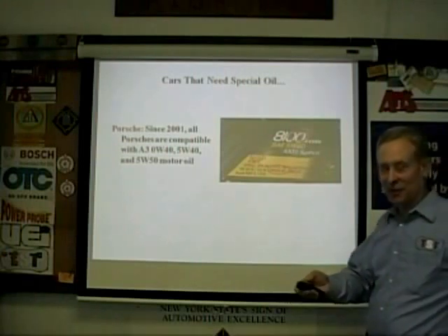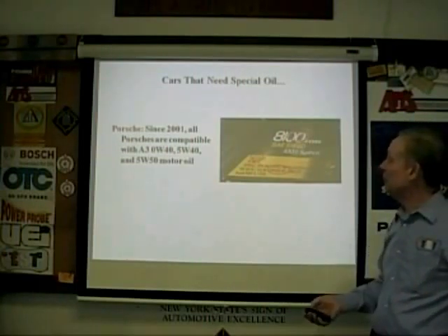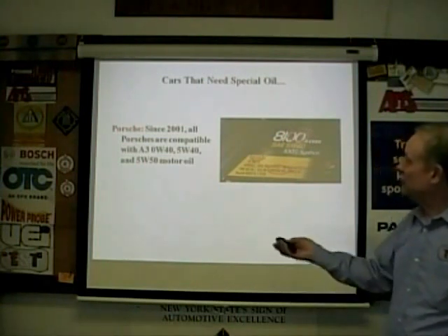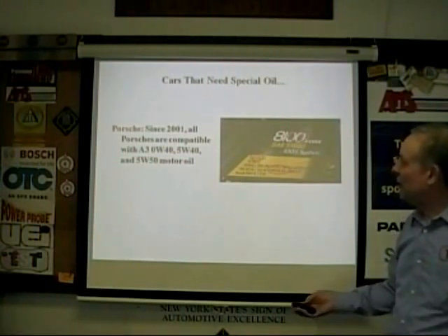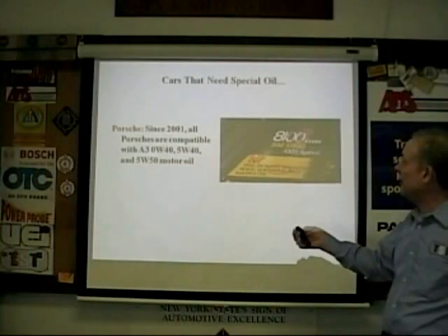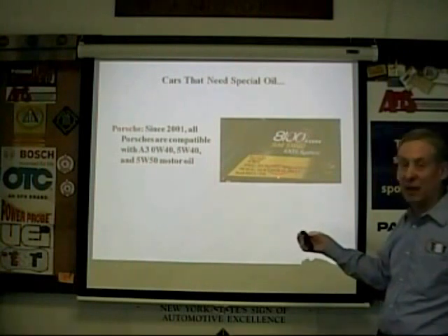I say cans, I'm not sure there are any cans anymore. They're all plastic things, but whatever. Porsche. Porsche is in a world of their own. They have this A3 040, 540, and 550 motor oils. Again, look for it. It's an ACEA A3 B4, and it's the Porsche spec as well.